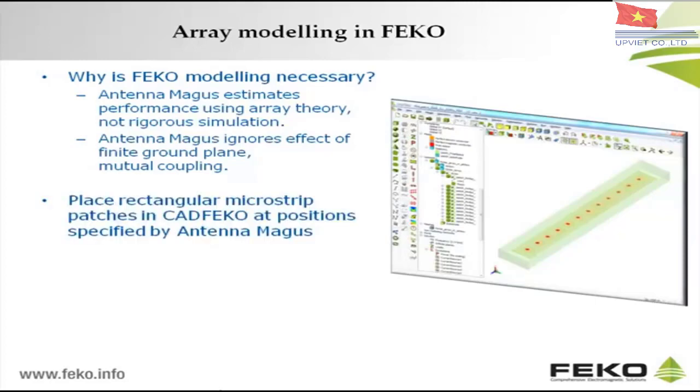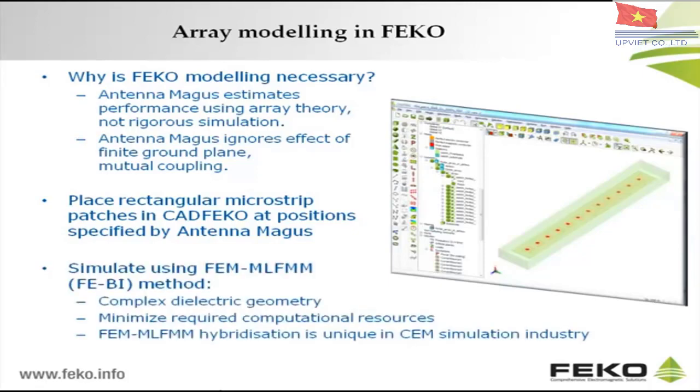Creating the geometry for a model of the microstrip array mounted on a finite ground plane is a simple task, utilizing the cuboid and rectangle geometry primitives in CADFEKO. We will use FR4 as a substrate.